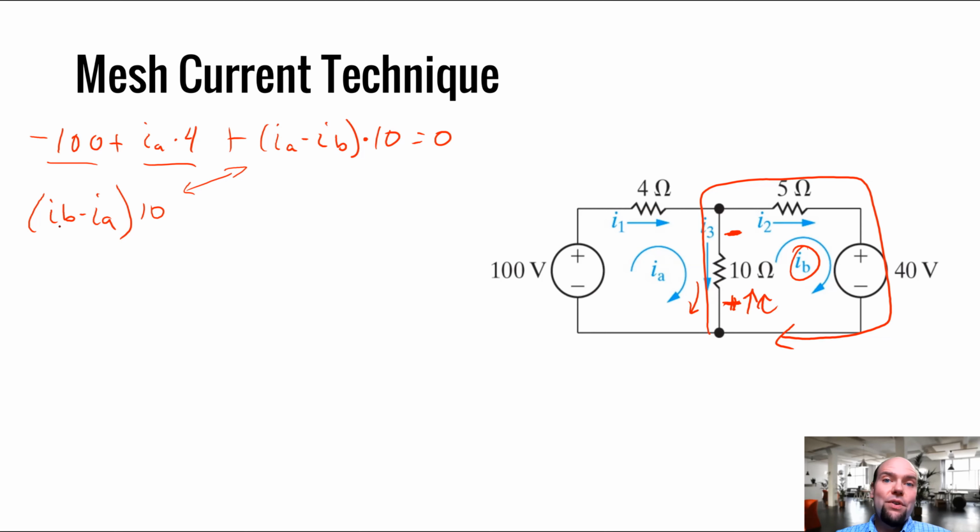So I always personally want to represent currents as flowing into the positive terminal. If I have a choice, and I can choose the current as represented flowing into the positive terminal, then I can just use V equals IR. So that's typically what I do. That's what I'm doing here: I am picking a way to represent my current such that it is entering the positive terminal so that I can use V equals IR.